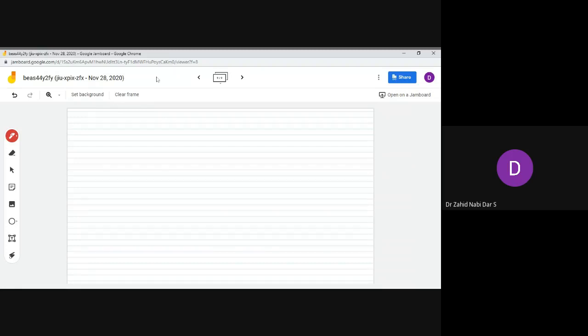As far as this is concerned, the number of coils per phase. Now you just came to know that the number of coils is 18. So one important thing is that for the winding details, for small machines, like very small machines, single layer winding is used. Single layer winding.